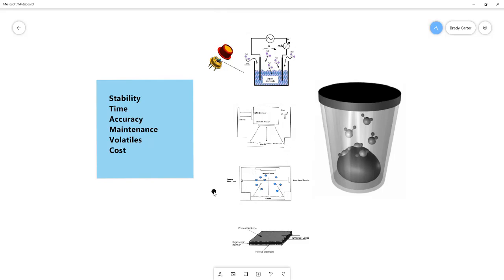And so now if we consider each of our distinguishing factors, when we talk about instrument stability, it's really, will I get the same answer every time? And that's influenced by outside factors like the user that's using it and whether or not he's getting the instrument dirty. In particular, the chilled mirror and even the tunable diode laser depend on cleanliness. The mirror and the infrared sensor can't make the right measurements if they're dirty. And so they are particularly susceptible to those kinds of factors.